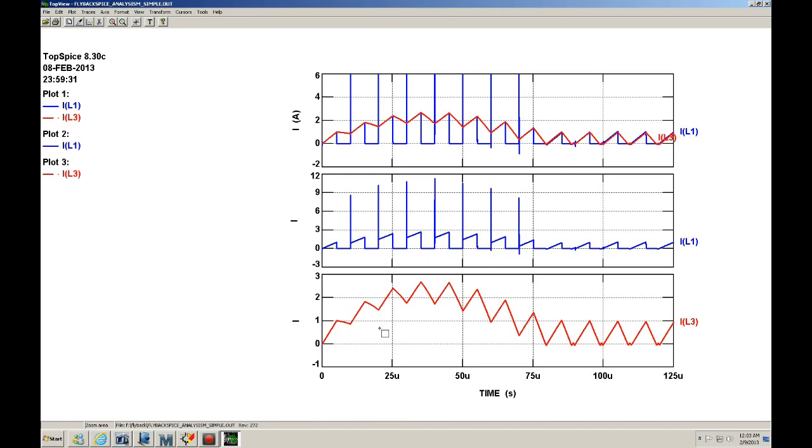Now keep in mind that this flyback that I'm designing is supposed to be a discontinuous one. Okay, and discontinuous means that all the flux in the transformer is used up. In other words, it goes to zero. That implies that the current in the primary has to go to zero. In other words, you stored all this energy in the primary during the time on, and then during the time off, you have to dissipate everything, or at least that's the idea.